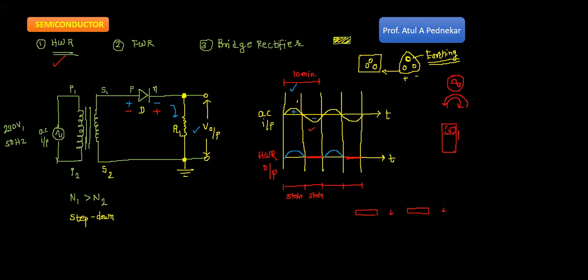Okay, I hope you are clear why it is known as a half wave rectifier. But when I look at the output of the rectifier, I can see certain peaks in it, or these speed breaker like shapes. But what I have learned is that for DC I should get a flat line. But I am not getting any flat line at the output. So how can we say that AC is converted to DC?